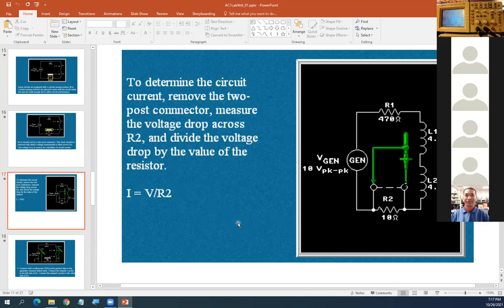Mr. Pham, if you use a DMM to measure the current, don't you have to break the R2? No, they already broke it for you. Well, when you measure the current, the meter has to be in series with the circuit. Without that one, you have to break the circuit here. The schematic shows the circuit broken. They already showed you the break right here. But then the current can still go through R2. Now they go this way. They go to the meter.